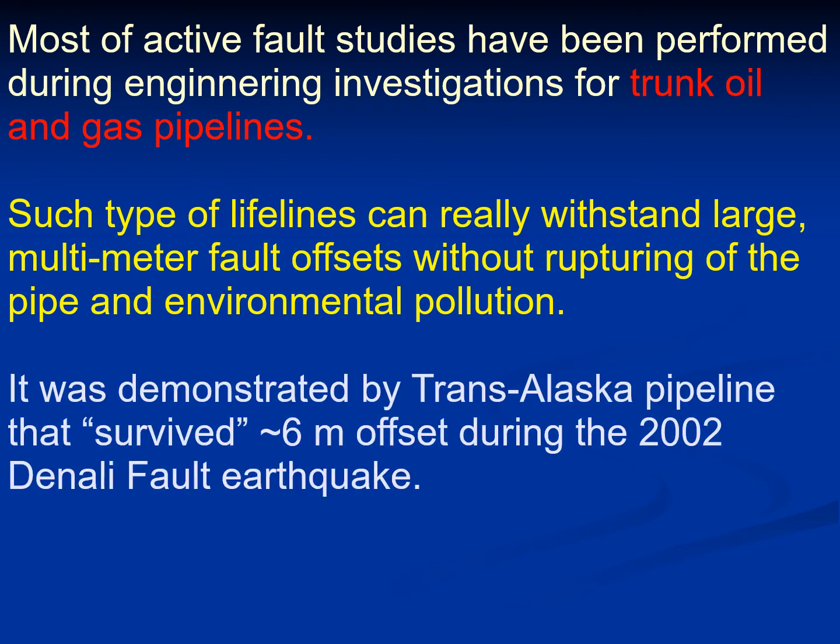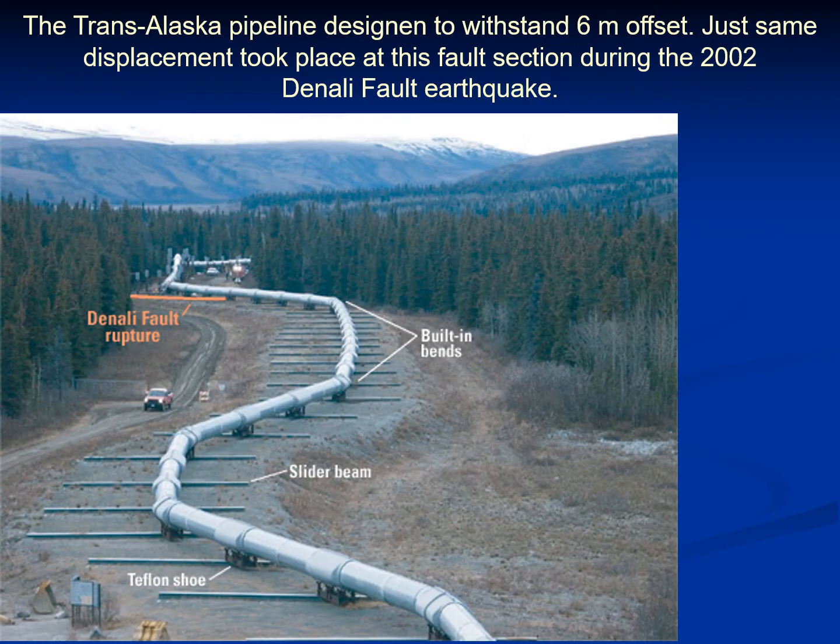And it was demonstrated directly by the Trans-Alaska Pipeline that survived about 6-meter offset during the 2002 Denali Fault earthquake. It is this section. It was directly designed to withstand 6-meter offset, and just the same displacement took place at this fault section during the 2002 earthquake.